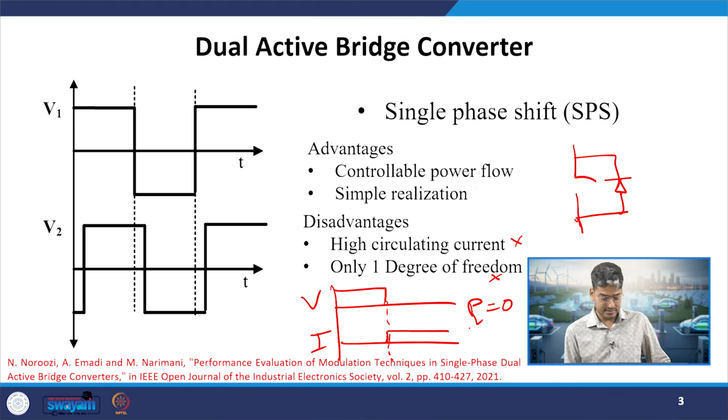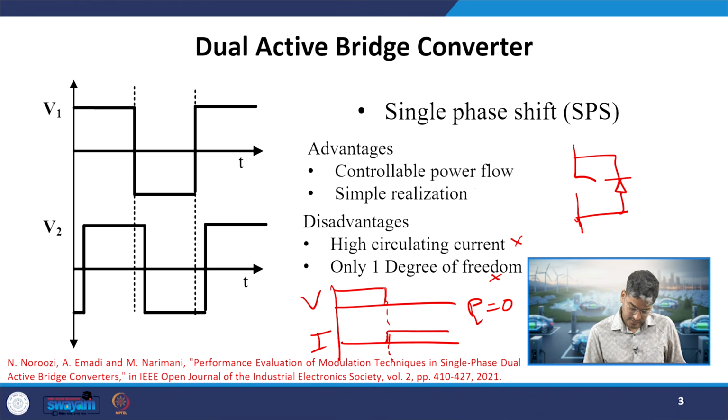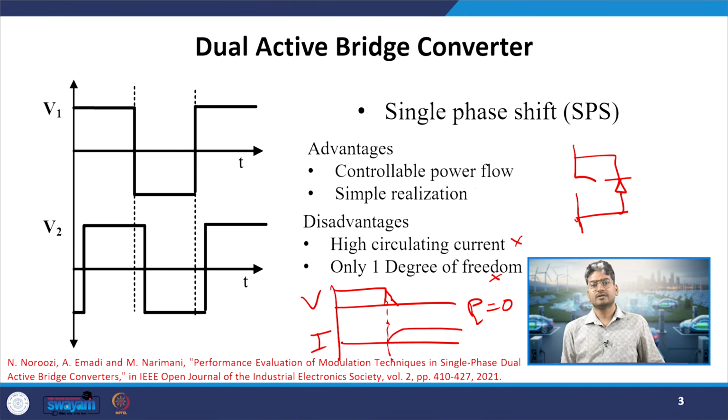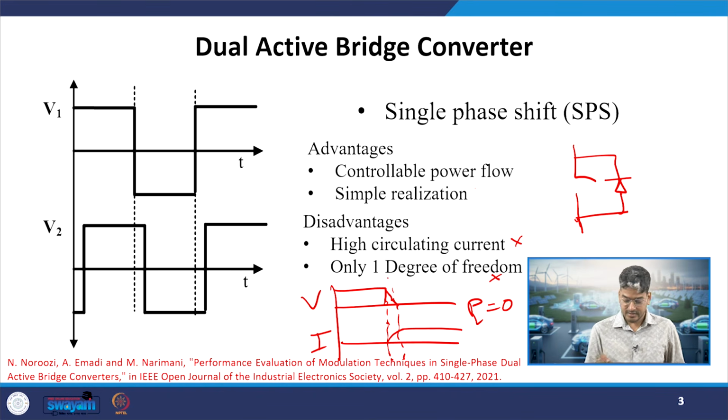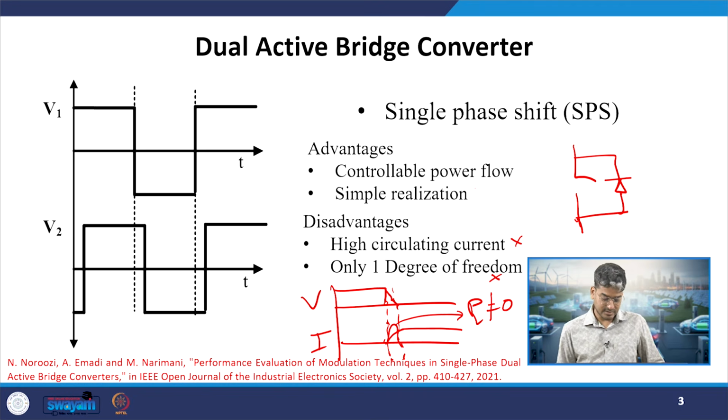Okay. So, this is the idealized circuit, but in the real case we will see that the voltage will have a sloping nature, it will not drop instantaneously and the current will be slowly picking up instead of going to the nominal steady state value instantaneously. So, we will have a common area. Okay. So, when I calculate the power loss in this circuit, I will see that there is a finite duration where both voltage and current are finite. So, we will get some power loss over here. Due to this, the product of these will be giving me the power loss component. Okay. So, it will not be equal to 0, we will have some type of loss in the circuit. Now, this is your normal switching or hard switching.